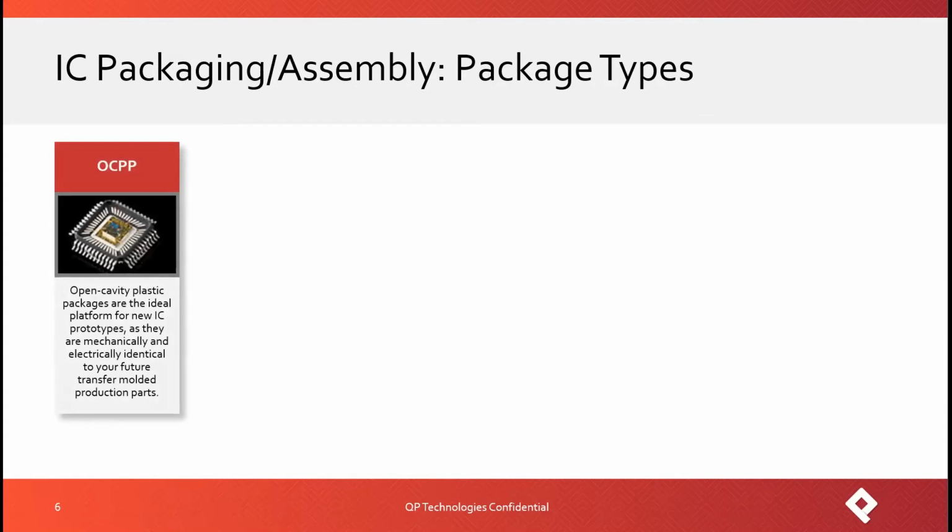Our legacy is actually something called OCPP, which really is taking an existing singulated, used package and reconfiguring it, our polite way of saying opening it, for reuse for a new die or a new device. That enables us to do things very quickly. It also enables us to work with just about any package of any type.